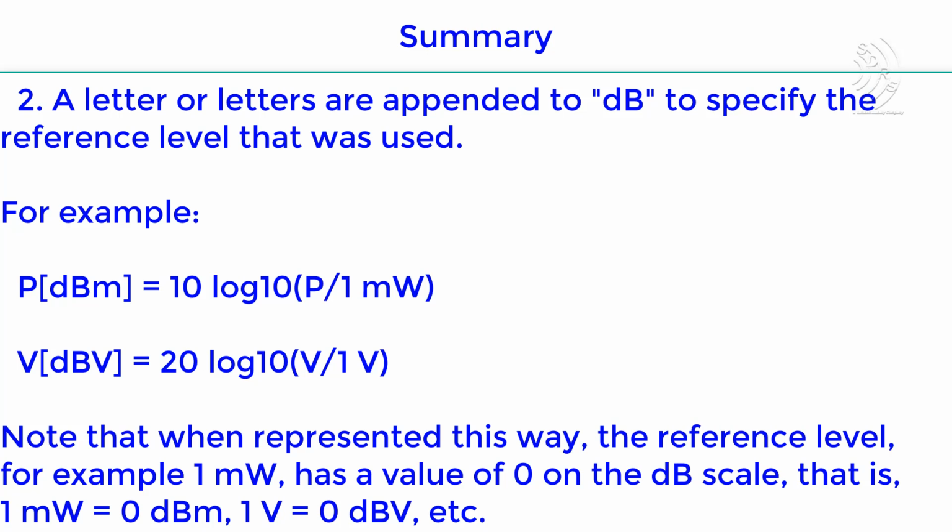Note that we use 20 times log 10 because we are working in volts rather than powers, and power is proportional to the square of voltage.